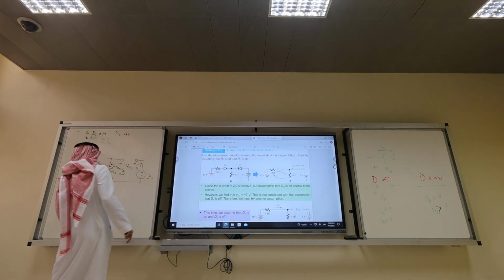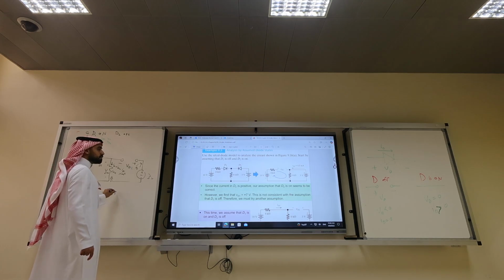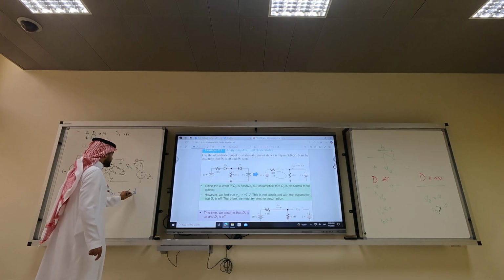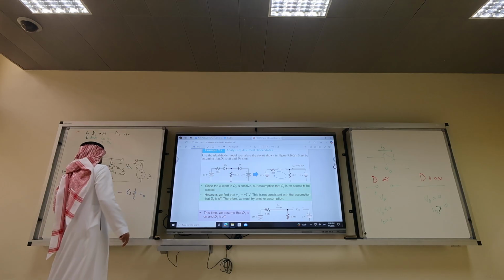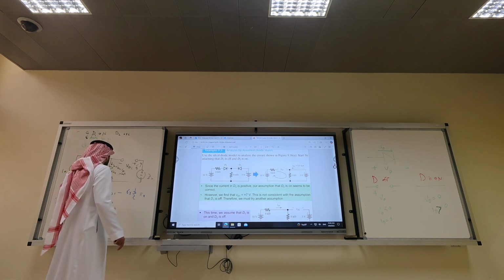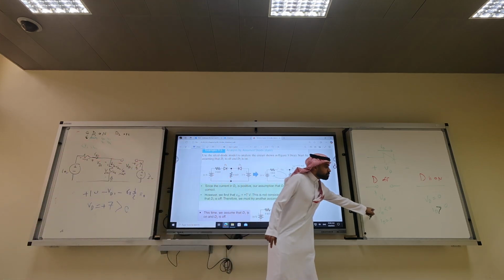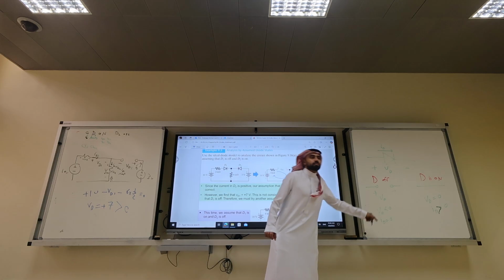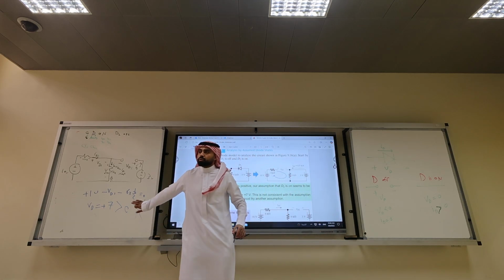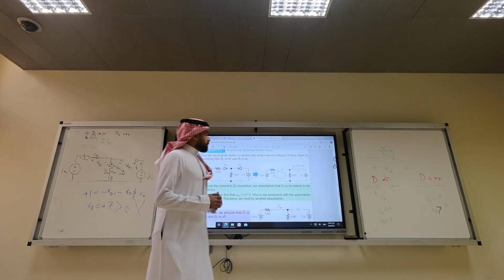Voltage rise plus 10 minus VD1 minus 6 times 3 half equals 0. So what is VD1? 10 minus 3, plus 7. It's larger than 0. This contradicts the condition. So immediately you say wrong assumption. Stop. Wrong assumption. Is it clear?